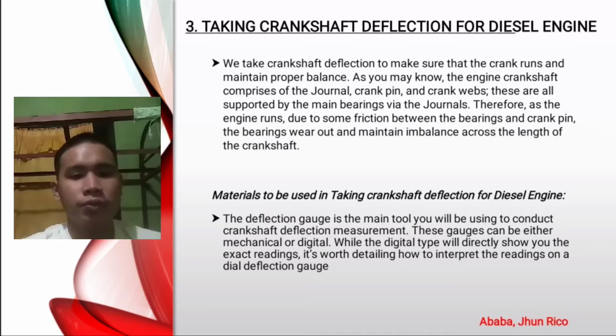It is to make sure that the crank runs and maintains proper balance, because as we know, while the engine runs, due to some friction between the bearing and the crank pin, the bearing wears out and causes imbalance across the length of the crankshaft.